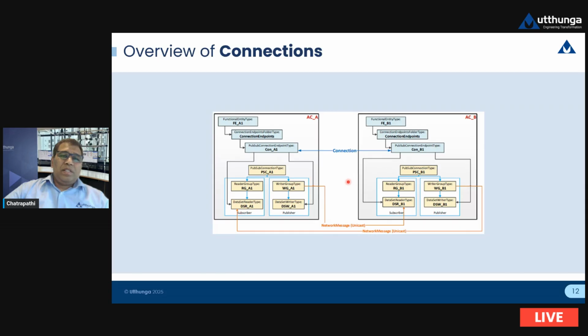So in this example, this is a bidirectional connection where the data is being exchanged over unicast UADP UDP messages. Here the writer group writes the data, and then the subscriber receives it on its port, then consumes it, propagates it and maps it to the corresponding nodes in the OPC UA address space.